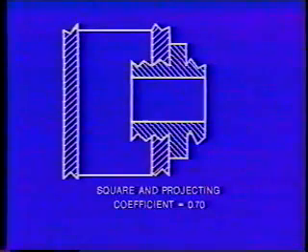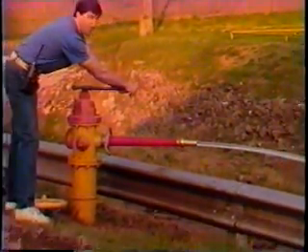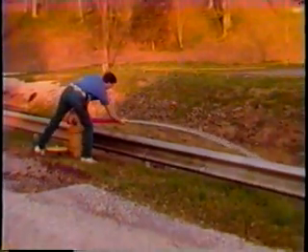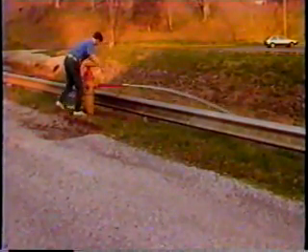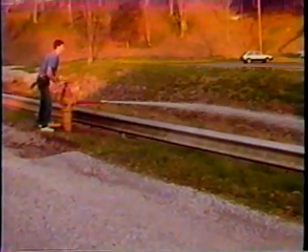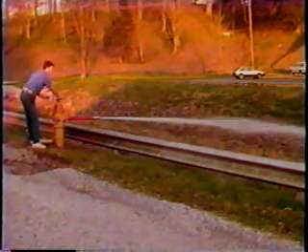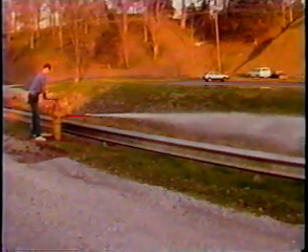Another type of hydrant is the wet-barreled hydrant. In this case, it's very difficult to precisely know the discharge coefficient because the operating mechanism is actually part of the outlet. For wet barrel hydrants, or hydrants for which you don't know the discharge coefficient, it's possible to attach some type of pipe to the outlet to smooth out the flow. In particular, an underwriter's play pipe, which you see here, is a good way to have a known discharge coefficient. It happens to be 0.97.